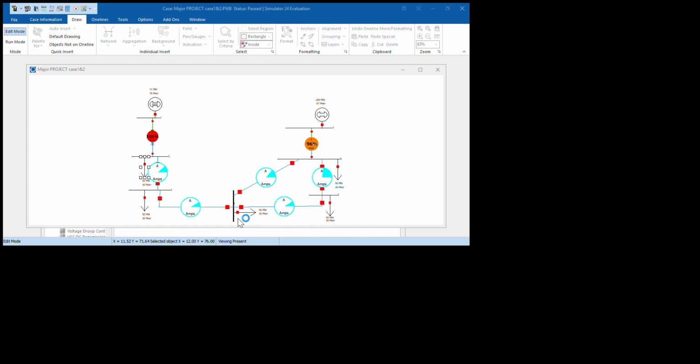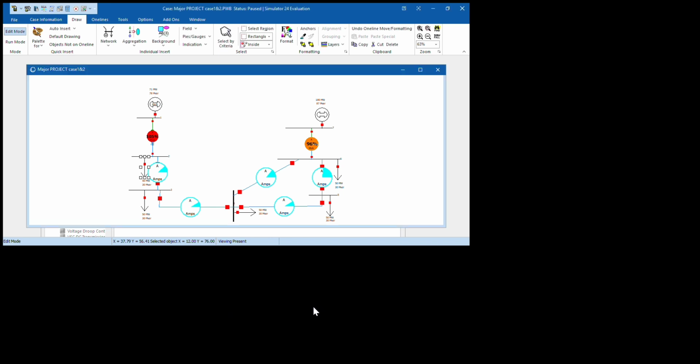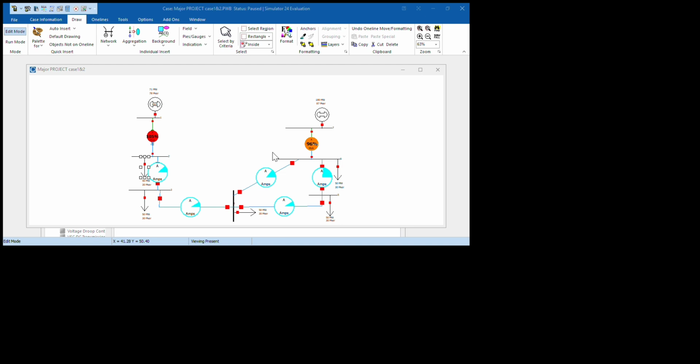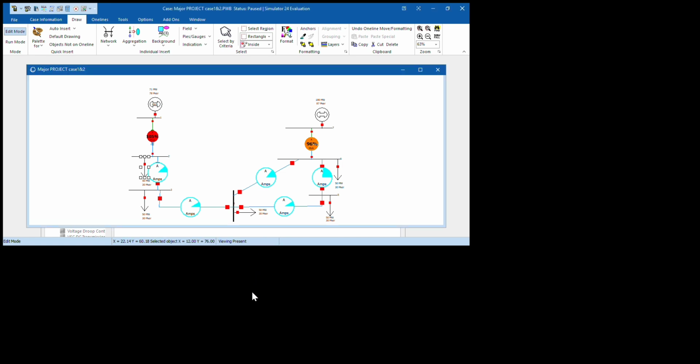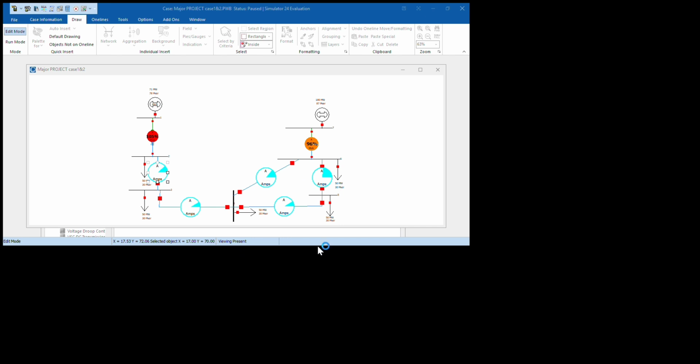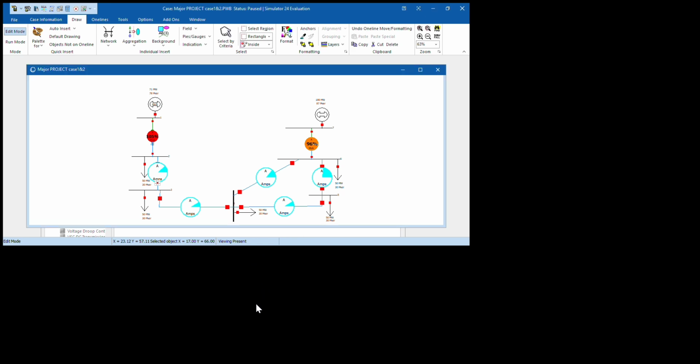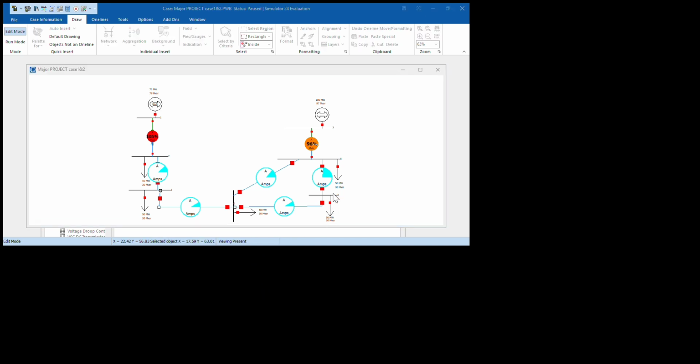At each bus we put 50 megawatt and 30 MVAR, which is the Q. Then last but not least, we will have the transmission lines from bus 2 until bus 6 interconnected like this, which will use the calculated values here for lines R, X, and then B. For example, for the first one, take this as an example: the R value, X value, and B value, which is the Z of line number 2 and the B2.